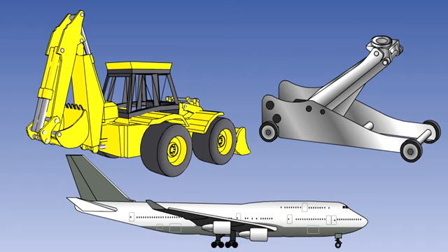Hydraulics is the science relating to the behaviour of liquids under various conditions. In aircraft, the hydraulic system provides a means of operating large and remote components that it would not be possible to operate satisfactorily by other means. Hydraulic systems provide the power for the operation of components such as landing gear, flaps, flight controls, wheel brakes, and other systems that require high power, accurate control and rapid response rates.